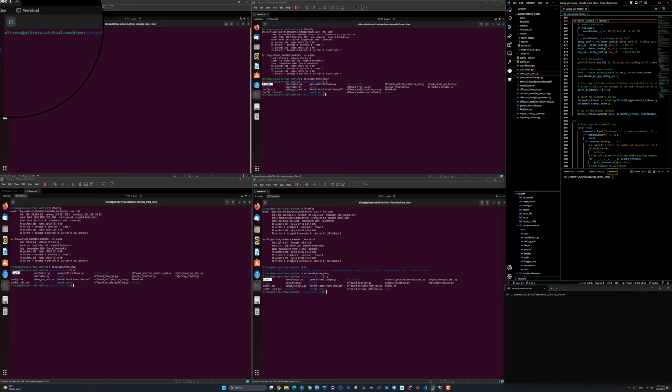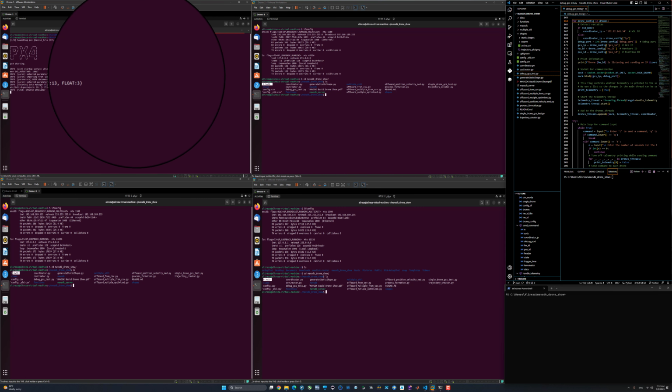Let's clear the terminal sections. We're gonna seed it to the PX4 firmware. Each one of these nodes, as I told you, has the PX4 environment installed. So if you don't have them, go ahead and watch the last tutorials on how you can set up your own software in the loop simulator. So each one of them has this JMAVSim, Gazebo, PX4 software as well.